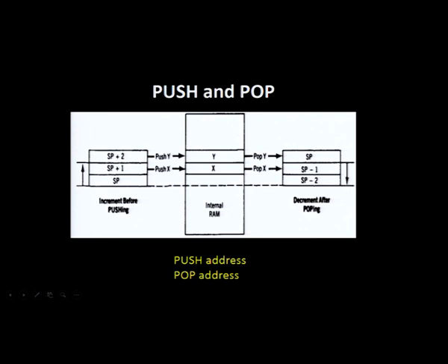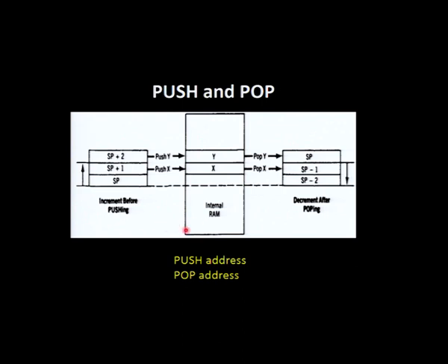In the data transfer instructions, a very important pair is push and pop. The push and pop instructions are used with the stack pointer. The stack is a temporary memory operated with the push and pop instructions on the principle of last in first out. So, the data you wrote last should be read first. Here, the memory's highest address is initialized, and after every operation the address will be increased, and that way the stack memory is used.